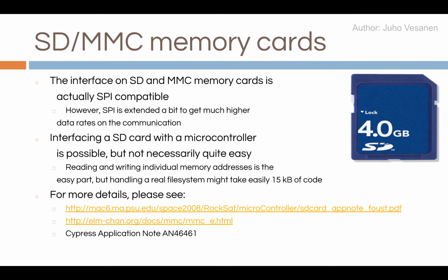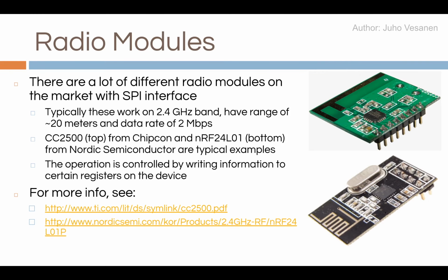SD and MMC memory cards use SPI. It's the SPI bus which reads or accesses the data on the SD card. Interfacing an SD card with a microcontroller is possible, and with PSoC it's relatively easy, since there is a component for interfacing memory cards.